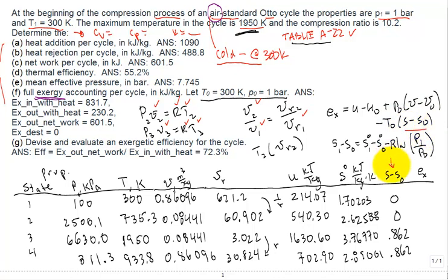That's this column. We multiply it by T naught, the dead state temperature in Kelvin, 300 Kelvin. Subtract that from V minus V naught. Well, the V naught is this V at state 1, because that's the same as the dead state. So you subtract that, multiply by the dead state pressure in kilopascal, so the units work. It'll be 100 kilopascal. And then U minus U naught. Well, we have all the tools. We go ahead and make the calculation of the exergy at state 1.